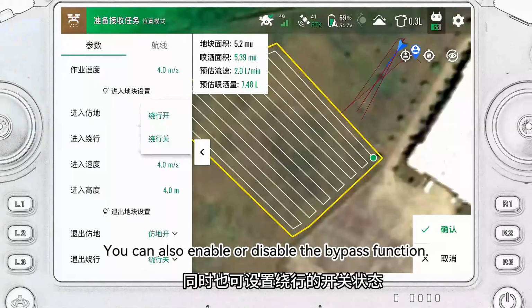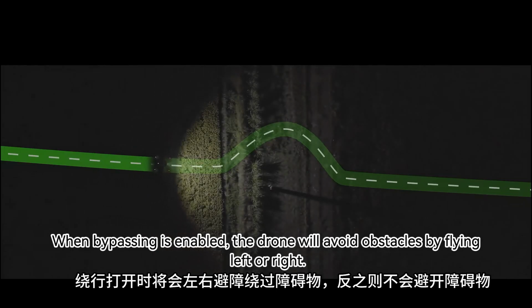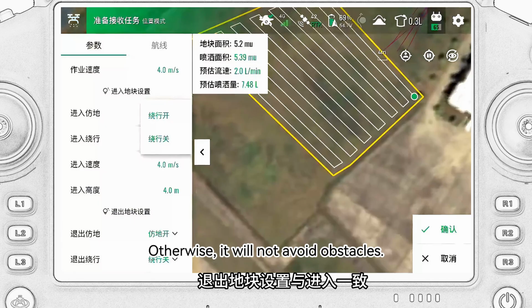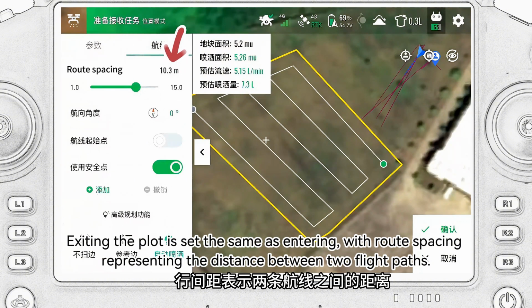You can also enable or disable the bypass function. When bypassing is enabled, the drone will avoid obstacles by flying left or right. Otherwise, it will not avoid obstacles. Exiting the plot is set the same as entering, with route spacing representing the distance between two flight paths.